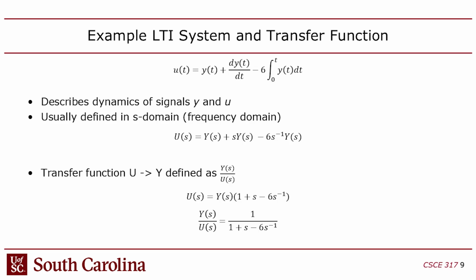they're typically transformed into the Laplace domain, or S domain. S is a complex variable, and it's basically frequency. So instead of being functions of time, they're a function of frequency. This makes them much easier to work with. Hopefully you guys remember this from electrical engineering. So whenever you have a derivative of a signal, you just multiply that by s. If it's a second derivative, it's s squared, and so on. If it's an integral, it's 1 over s, or s to the negative first power. Second integral is s to the negative second power, and so forth. And you're just multiplying that by the name of the signal.